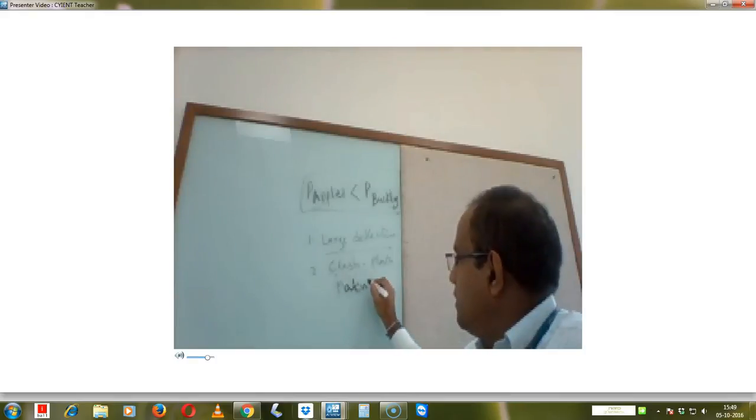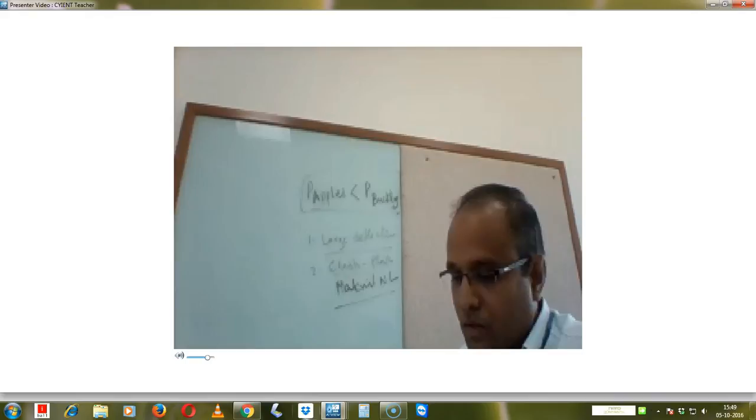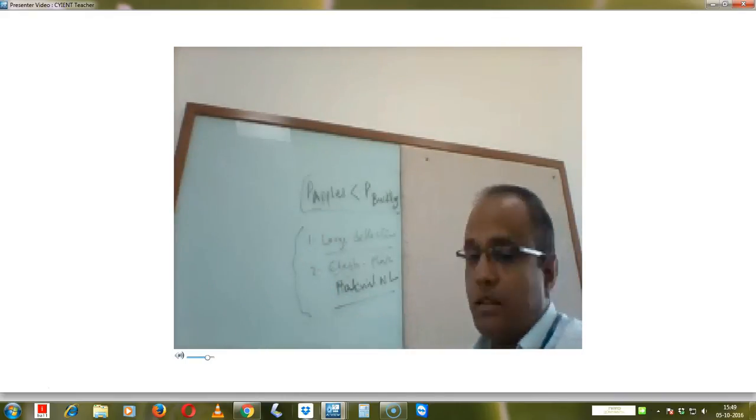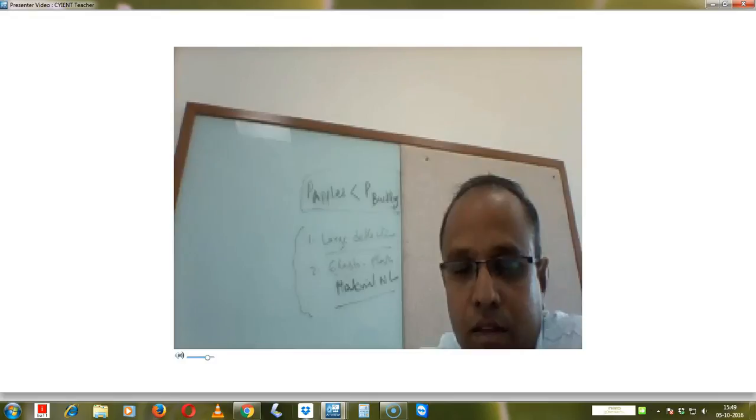Material nonlinearity. Okay. So it will account for both large deflection and material nonlinearity. Because nonlinearity is accounted for here, it predicts accurate buckling load. For this type of analysis, note that small off-axis loads are necessary to initiate the desired buckling behavior.